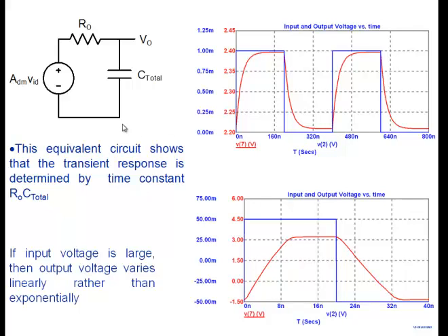So the issue is what happened. Obviously, this model has failed, because this is the exponential characteristics, and now this is linear here. So why has it failed, and what is this phenomenon here? Now, many of you may already know that when output voltage changes linearly like this, we call this a slew rate. Slew rate in an op amp, you must have heard earlier. The op amp charges linearly like this, discharges linearly here. So this phenomenon is called a slew rate.